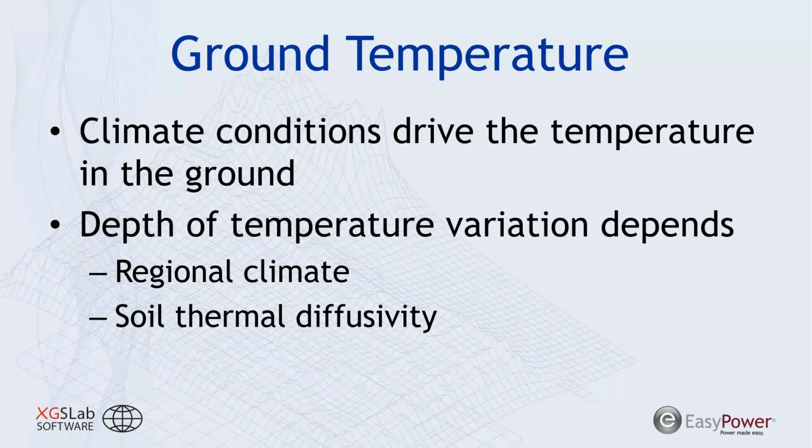So what really drives the temperature of that soil is going to be our climate. So when we're performing those measurements that we talked about earlier, it's a little bit of a historical measurement. We're measuring the soil resistivity, and as we go deeper, we're starting to measure a little bit of the climatic conditions a week ago, a month ago, or a year ago, based on some of the regional climate of that area and that soil's thermal properties.